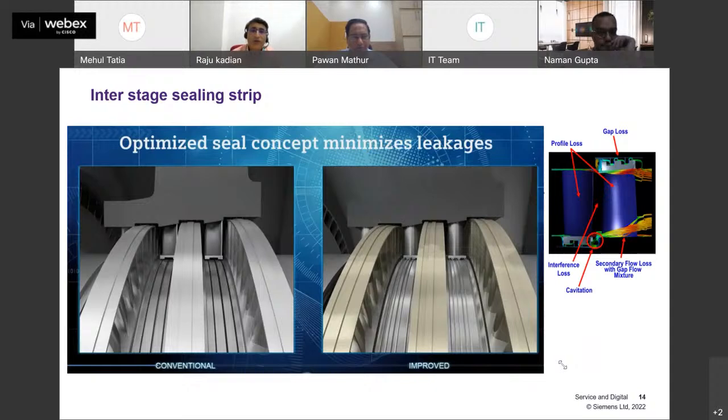This gives the overview, as I talked about in my earlier slides, from the left, that is the conventional design, to the improved design. You can find out from the shape of the shroud on the moving blade, which are generally self-shrouded blades, and on the shrouds of diaphragms, there are more seals. These are possible due to optimized design of turbine casing and guide blade carriers to get minimum thermal expansion values, differential expansion values.